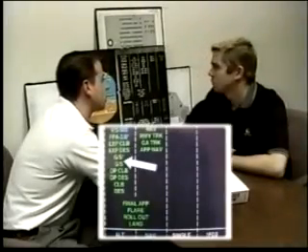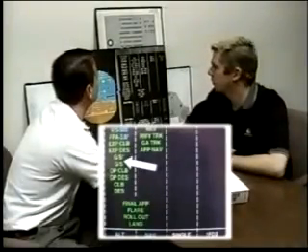Glide slope? Glide slope start? That just means it's engaging the glide slope. It's received the glide slope signal and it's just going to fly the glide slope down. Works similar to the flight path angle, actually.